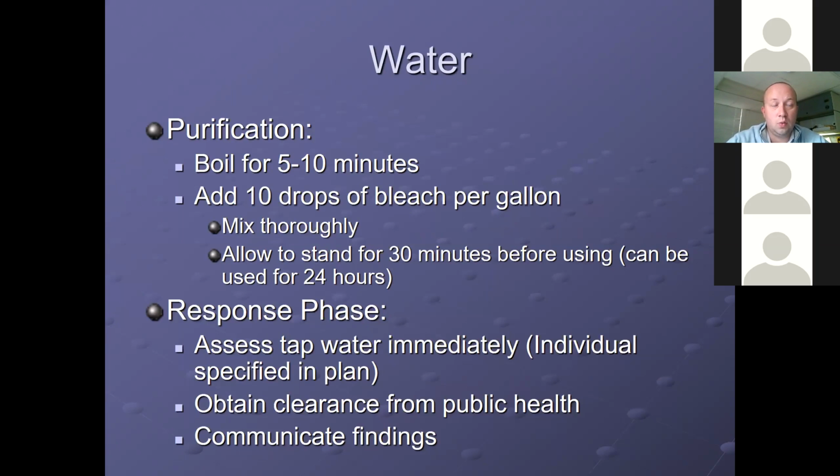One of the reasons why we have so many water main breaks or water line breaks when you lose water is that you have a damaged pipe that's somewhat being held together by a constant pressure. When that pressure dramatically drops, it can actually create a suction and suck the pipe in, and then when the water pressure expands, it can create another air pressure pocket, and oftentimes it's the air pressure moving through, not the actual water, that can cause a water pipe to blow.